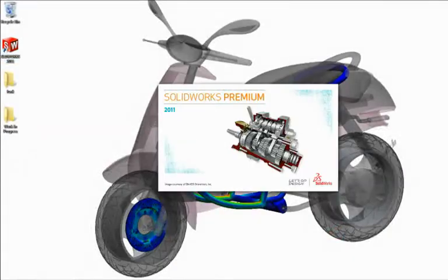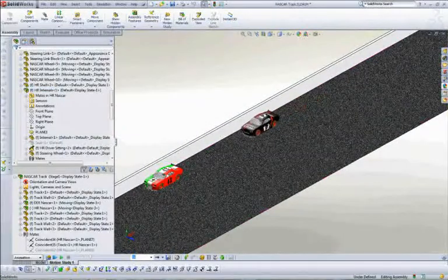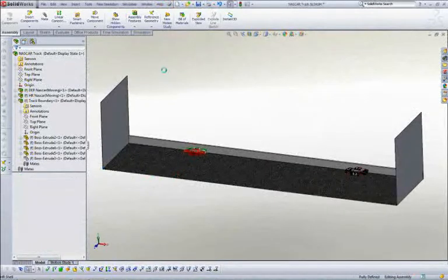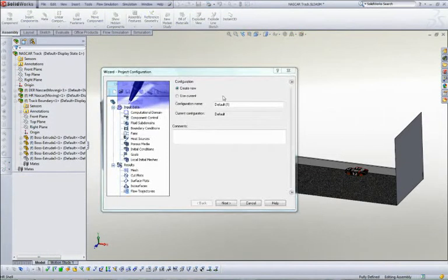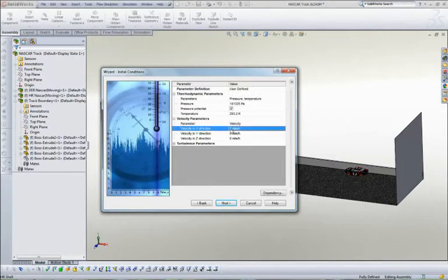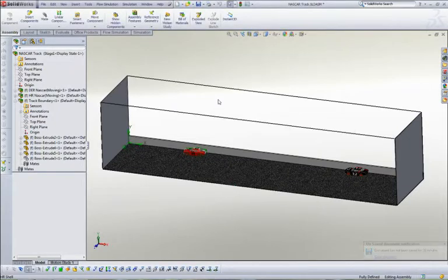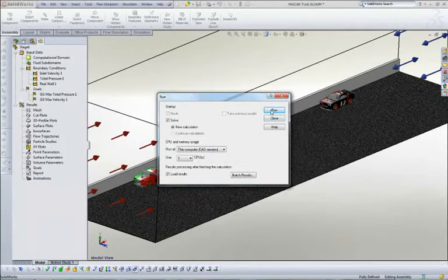Now, Jimmy hates not knowing, so he fires up SolidWorks to find the answer to Lucy's seemingly simple question, but a question that involves some pretty complex aerodynamics. Using flow simulation to solve Lucy's problem is very straightforward. In effect, we are making a virtual wind tunnel. And just like a wind tunnel, we have to set the car speed as the air velocity, in this case, 150 miles per hour. And after setting the road and walls conditions, Jimmy is ready to solve this problem.